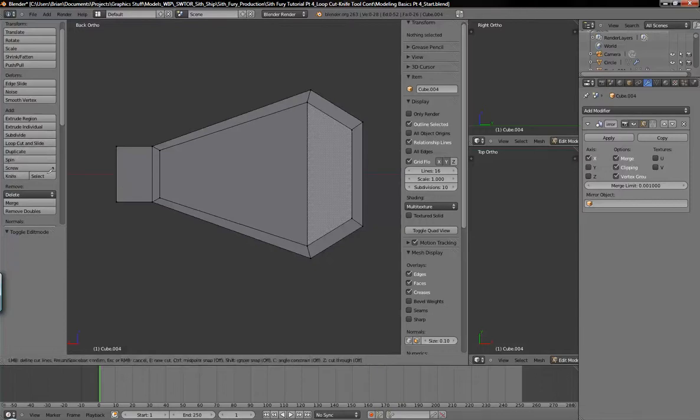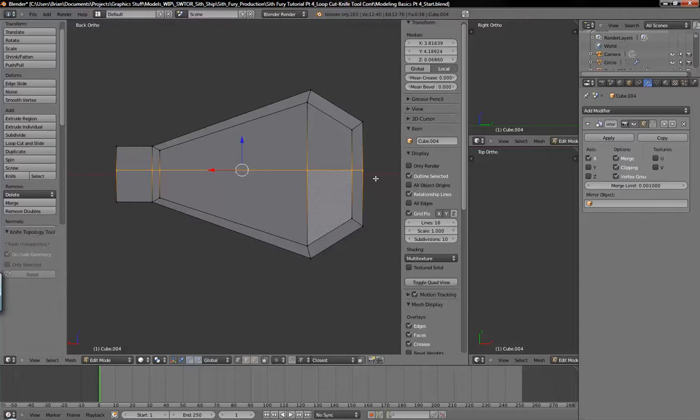And see, knife. Do about right there. Let's see. Give us a straight line. I'm going to hit Z to cut through. And we'll just left click and then spacebar. And we'll do one more. Knife. C to constrain, Z to cut through, and then left click and spacebar.